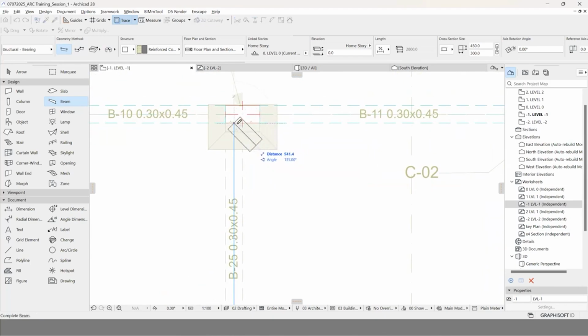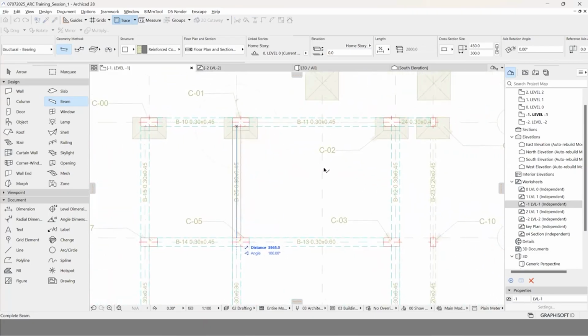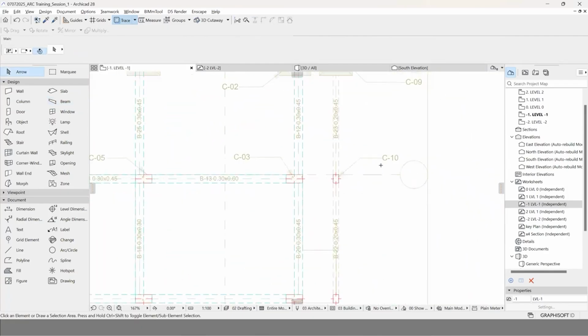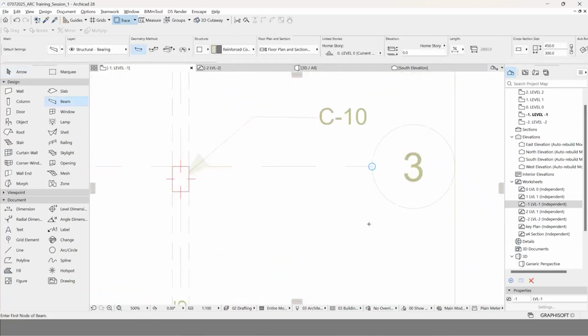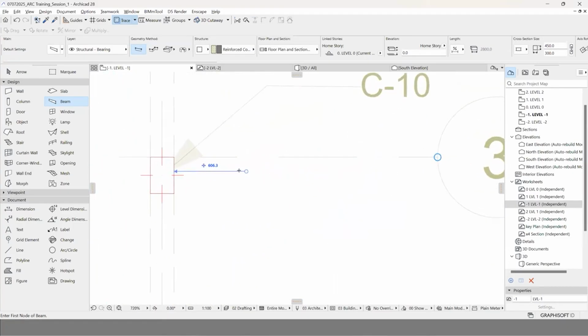Now I know exactly where it is ending, so I can start from here and I can do it. Because I did a line, it is like this. What if it was a point? It would have been completely different. So if I hold here on the point, it will create a circle. Now from that circle, I get a straight line here, I get a straight line here, I also get a line in 45 degree. So there are many methods in which you can create these guides. If I want to find the center of these 2 points, I can keep the cursor here, it will create a circle. I keep my cursor here, it will create a circle there. And when I move to the center, I will find the center point in this. So you can see it is also going to be snapped to that point as well.